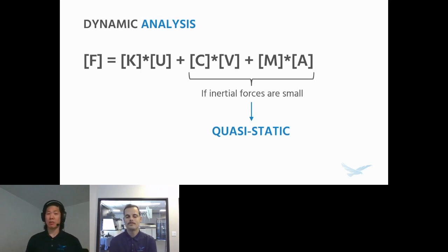We're not quite keeping those forces truly zero, like in a pure static analysis, but they're small enough that the overall effect on the result shouldn't be too large, and we're able to solve the analysis by using those dynamic inertial forces to balance the equation. Okay, and so this is the first approach that you might want to think about when you're dealing with extreme deformation, is taking a dynamic quasi-static approach rather than a true static approach.